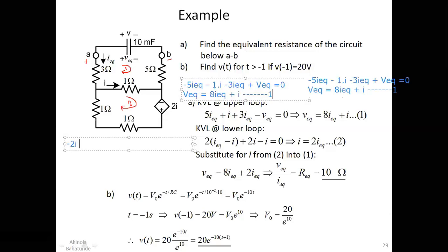And then if we go down, you realize that, okay, now before we go ahead, there's a problem here we have to solve. There's a current coming in, this is a node, don't forget, we can treat this as a node. So we don't have any current defined in the second loop. Okay, so we have to define it ourselves. So we can apply KCL at this node. We know the current coming into this node. We know the current leaving this particular node. Okay, so we can say let there be another current going down in this particular node here.